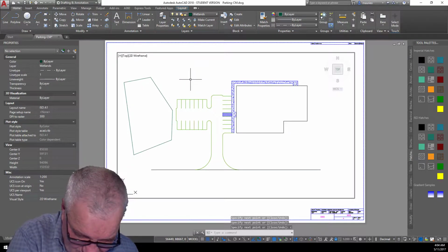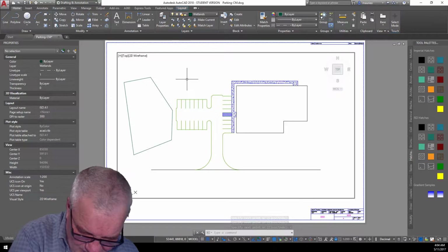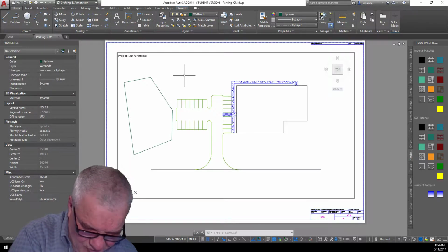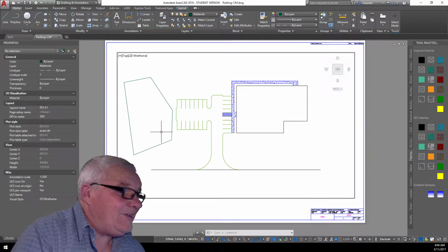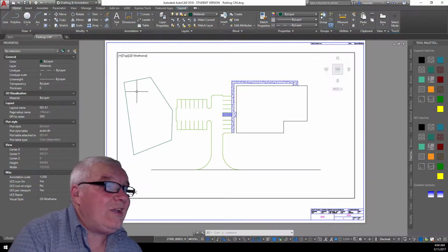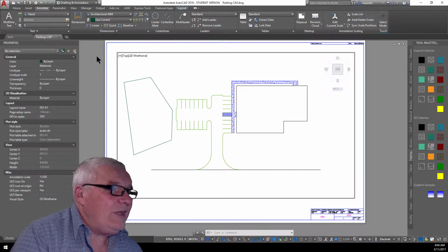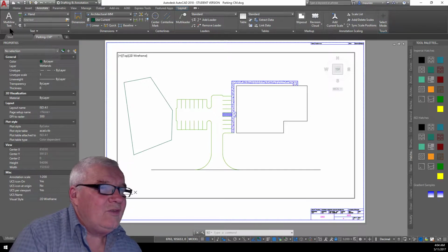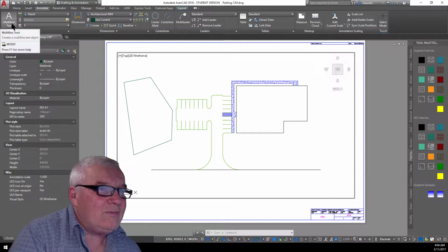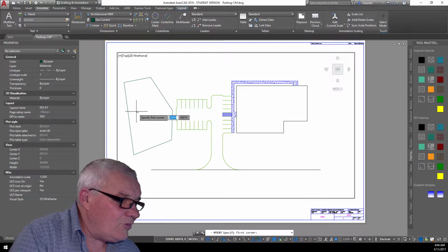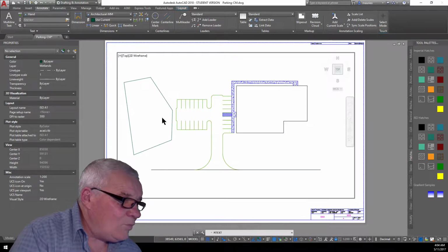Yep, we've done that. Add the text wetland inside and hatch the area with the swamp pattern. So add the text wetlands, annotate. Alright, and well, multi-line text, and we'll just add that in there.